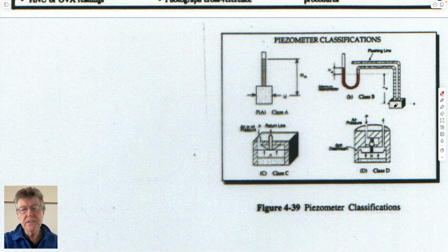And if this is measuring tension or negative pressure in the water in a soil, then you need to couple it to a manometer, which can measure negative pressures. Piezometers, in terms of water levels, can only measure positive pressures as a height above the datum, whatever that is. So a tensiometer would measure the suction in a soil, negative pressures, and it would use a manometer, probably not with mercury in it, but probably with water in it.